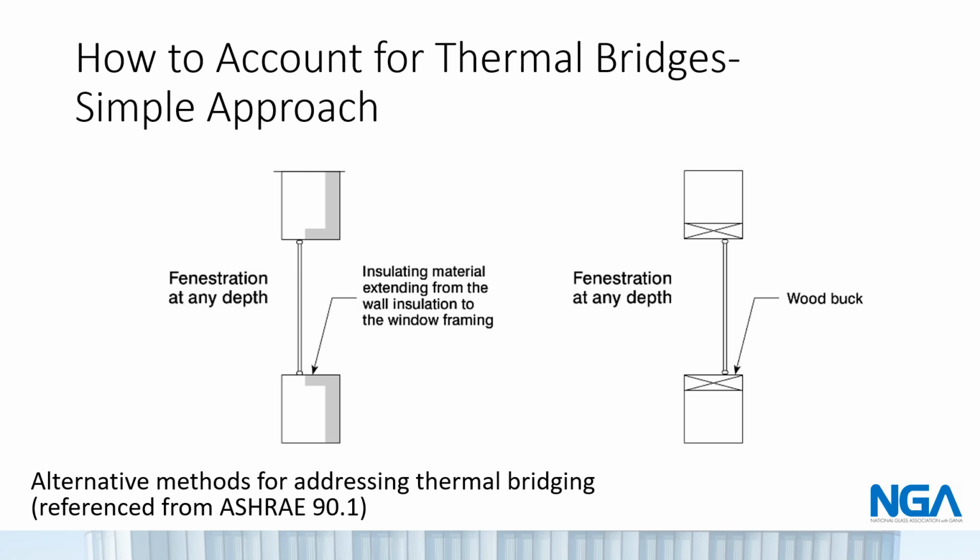It is not required that the insulation be under the frame, as careful consideration must be given to the attachment and support of the window, as well as proper water drainage. In all cases, the intent is to maintain a continuous thermal line as much as possible and to minimize interruption of the thermal line, thus creating thermally bridged details.